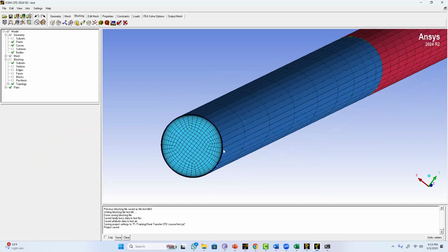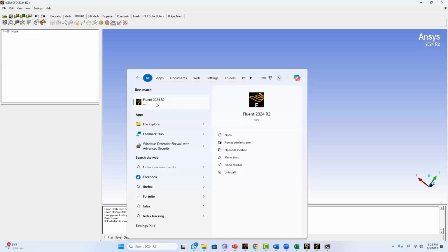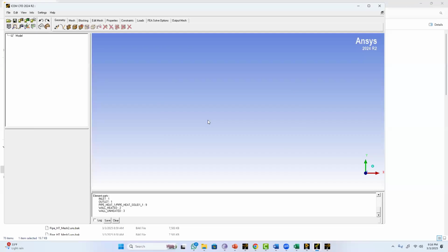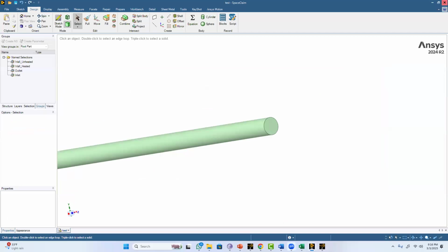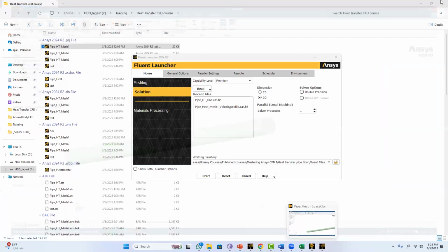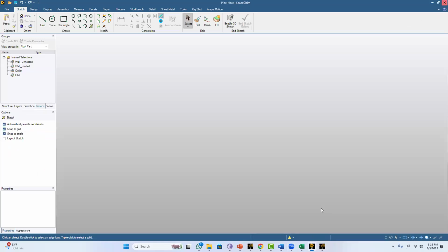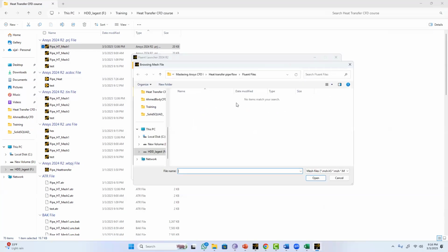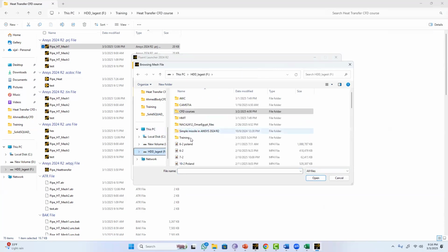Okay. So now I'm going to open a fresh Fluent copy. We start from scratch. So close everything here as well, and I will just read our first mesh file. There are three mesh files: mesh one, mesh two, mesh three. Those are the coarse, medium, and fine meshes. So read the mesh file, and make it all files. Sorry, this is here.